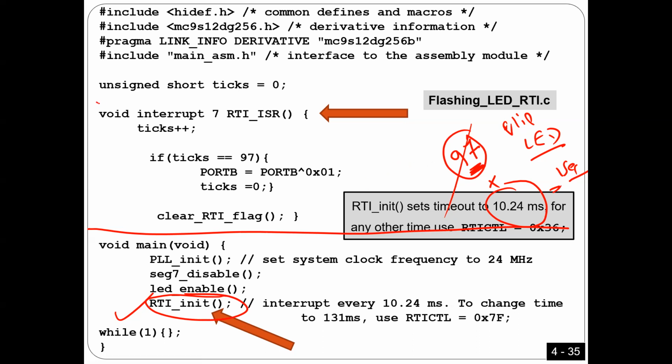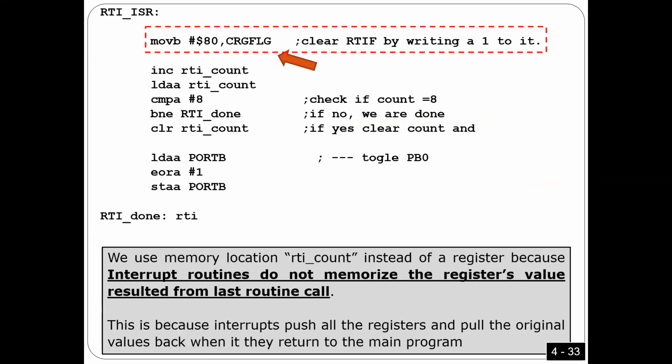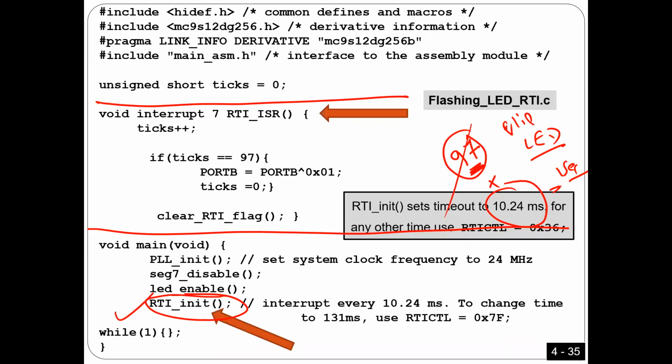So that's what I did here. If you look here, guys, inside the subroutine I have a counter similar to RTI count. I need to count this interrupt 1, interrupt 2, interrupt 3, and so on. I'm going to call it tick, just any name. This tick is the counter. Every time there is an interrupt here, I increment the tick.